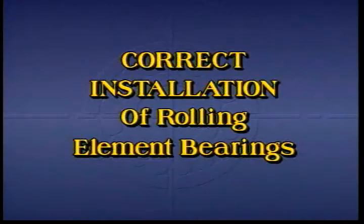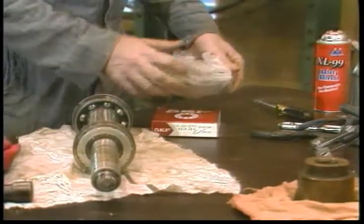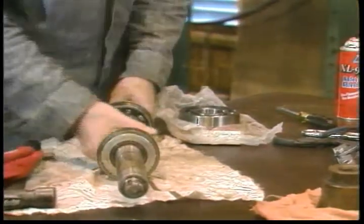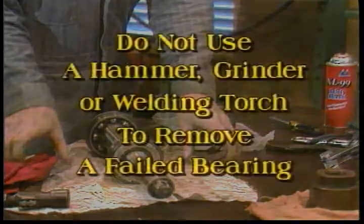Like plain bearings, rolling element bearings must not be distorted during installation. Both rings must be firmly supported by a perfectly round bore and shaft. This means that when you remove a failed bearing for a replacement, you must be careful not to damage the bore or shaft in any way.